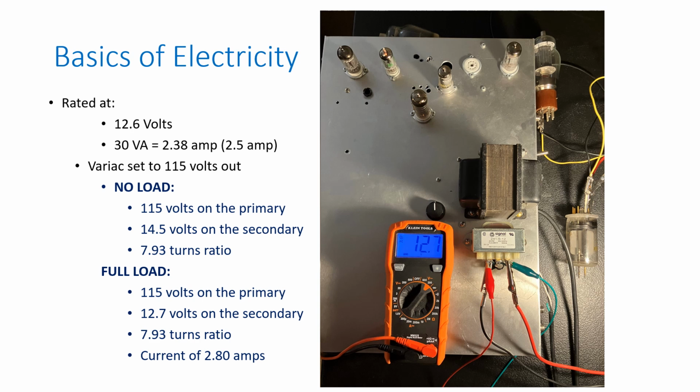The reason is the transformer that feeds the house is rated, like this one, in volt amps, but it's a 240 volt transformer rated for 25,000 volt amps. So if I draw 100 amps, that's only a fraction of the rating of the transformer. So for the most part, most of the time, I'm hardly loading the transformer at all.